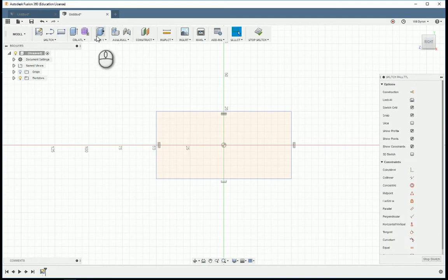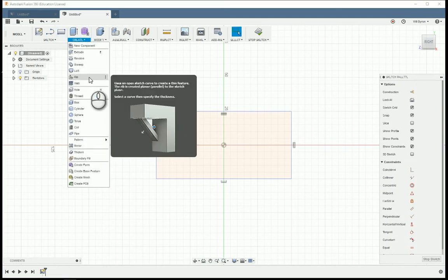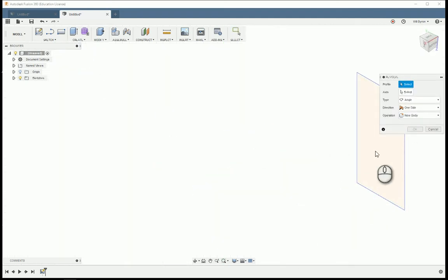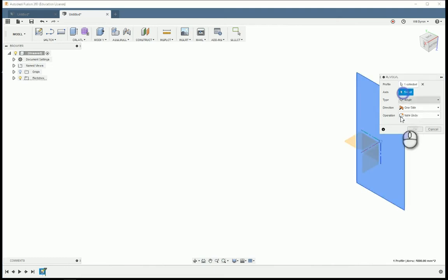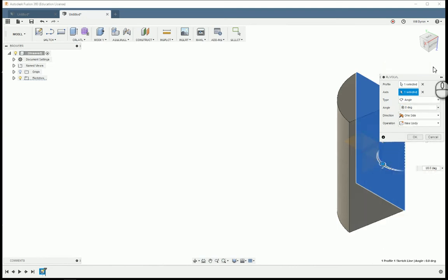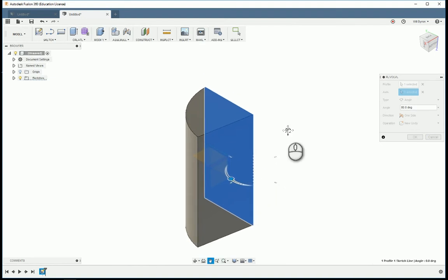One last thing, and then I'm gonna try and finish up. The revolve tool. Take a 2D face, specify whatever axis you want to rotate it around, and specify the angle that you want to go off of. Just for giggles, don't forget about your pan tool. Pan is how you actually move in the frame. This is what it would look like if I wanted to create a half cylinder, or I specify 80 degrees.